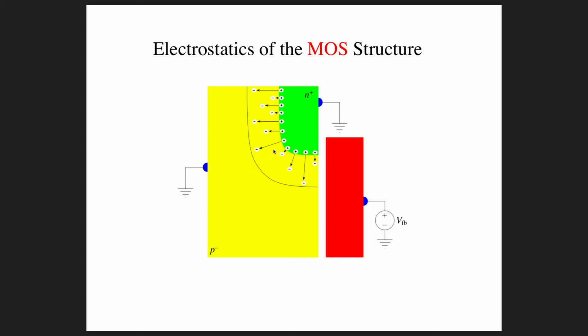And we wind up creating this depletion region here, devoid of mobile carriers, where we have these exposed space charges creating an electric field which opposes the diffusion of these carriers down their concentration gradients. Okay, so we have this built-in potential, which we talked about before.